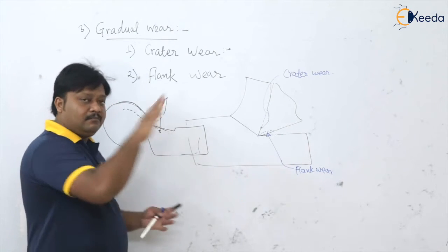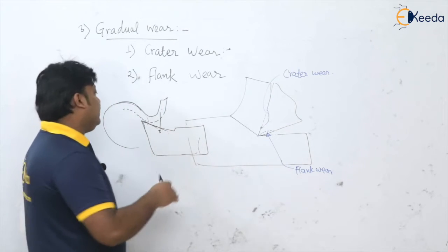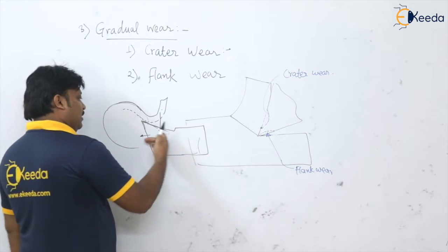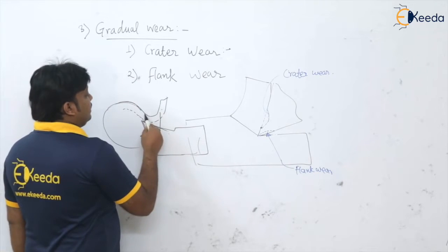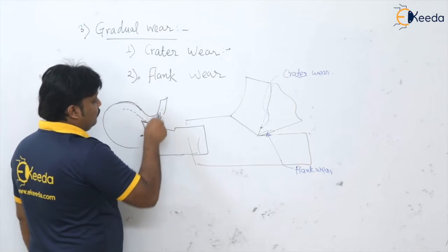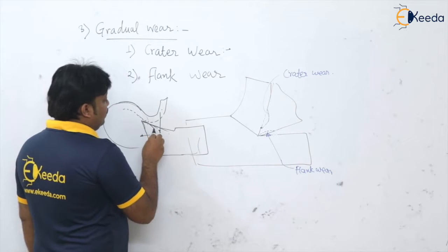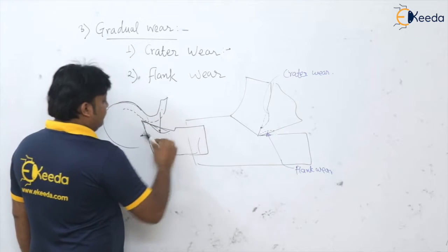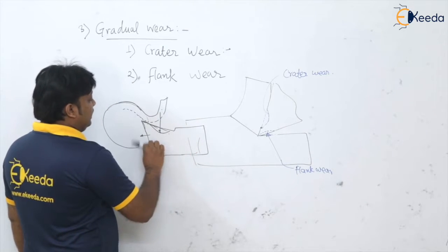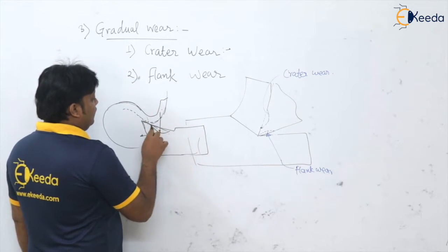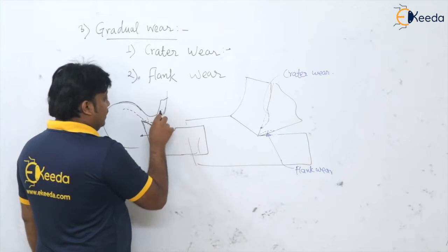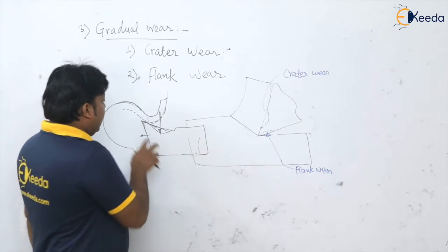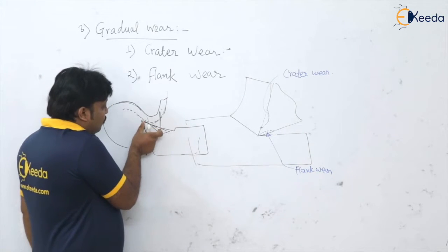And this is happening continuously, that is, whenever the tool is penetrating into the workpiece, it is constantly lifting the chip up, and because of self weight it is falling down. So there is continuous contact, and of course the tool is given the feed F, so the tip is always moving ahead, and this chip is always lifting up and striking back onto the rake face at a certain distance from the tip of the tool.